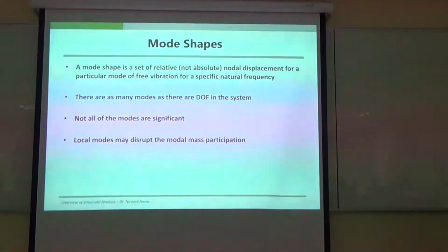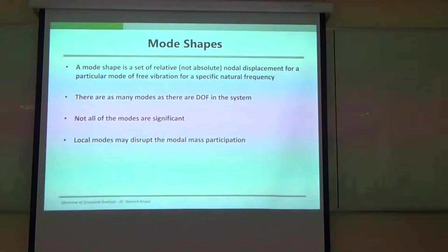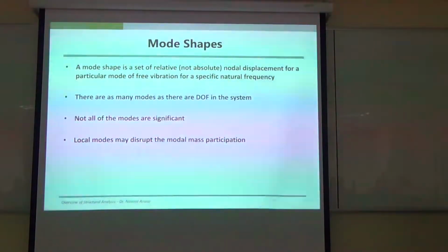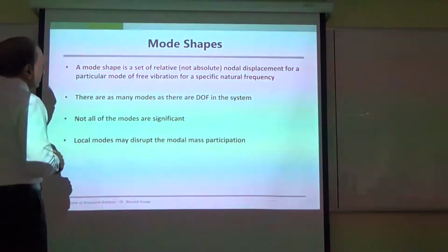And that is a good trick. I mean, it requires some understanding. What modes are we looking for and how to extract the relevant modes from the model? Because in SAP, in any tabs, when you're looking at the model analysis, you can specify the frequency range that you're looking for. So you can be looking at the global range or local range or a particular range. So you can find those frequencies or mode shapes.